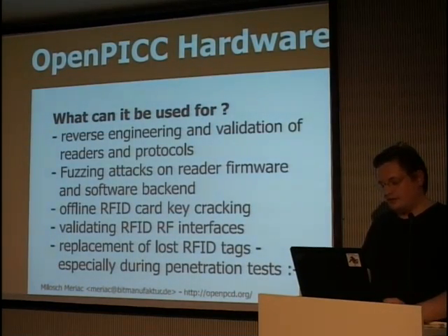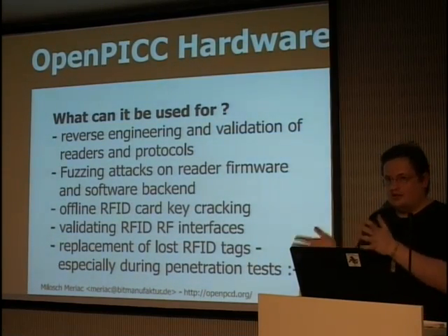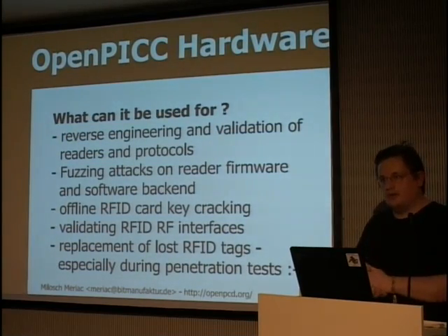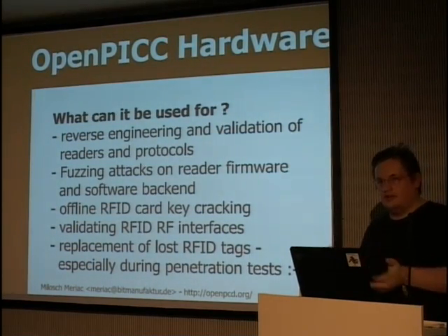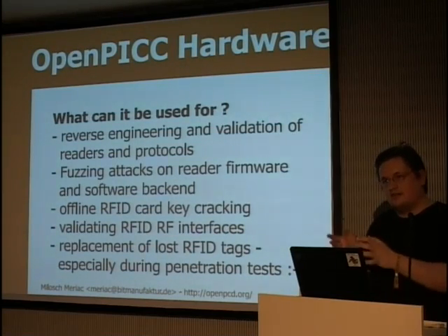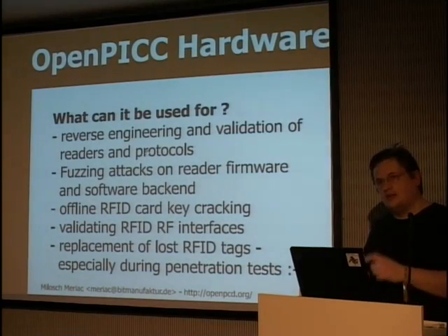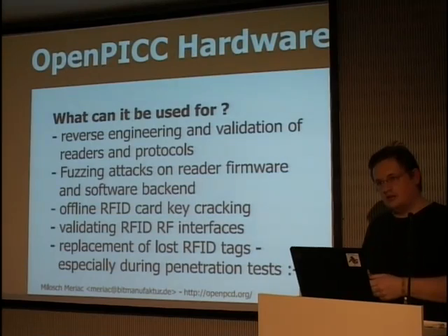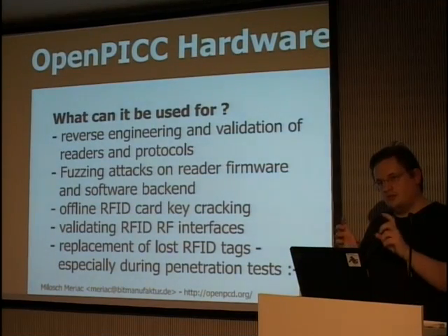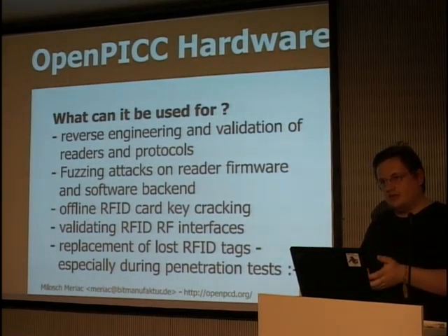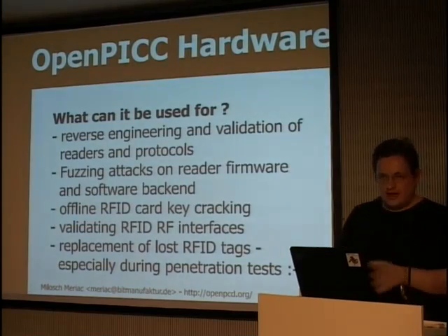Okay, so the basic idea was naturally reverse engineering. This means if you, for example, examine the protocol of MIFARE, at one point you have the opinion, okay, it could work like this, and then you can use this device to instantly test your assumptions. So this is a tool for iteratively reverse engineering protocols, and you find out what's important in a protocol and what's not. Because we have this, we can actually demodulate the reader data that we see. You can also use it as a dumb sniffer.